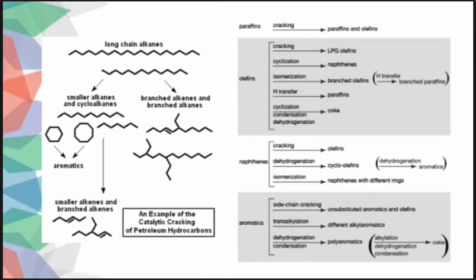The fluid catalytic cracking process breaks large hydrocarbons by their conversion to carbocations, which undergo a lot of rearrangements. The figure shown is a simplified schematic diagram that exemplifies how the process breaks high boiling point straight chain alkanes, which are also called paraffins, into smaller straight chain alkanes, as well as branch chain alkanes, olefins, and also cycloalkanes. Some of the smaller alkanes are then broken and converted into even smaller alkenes and branch alkenes, such as the gases ethylene, propylene, butylene, and also isobutylene. The olefinic gases are valuable for use as petrochemical feedstocks.